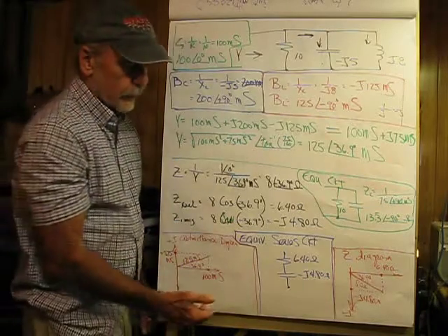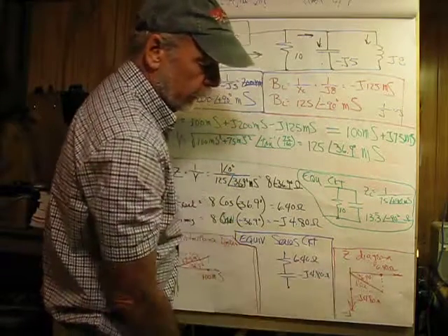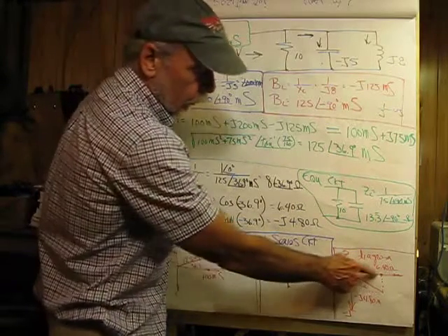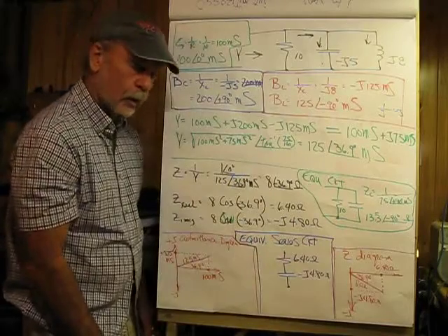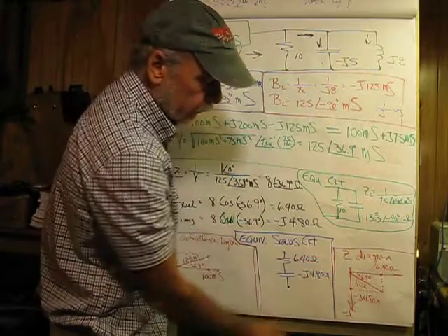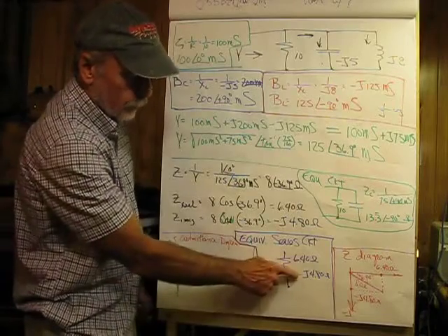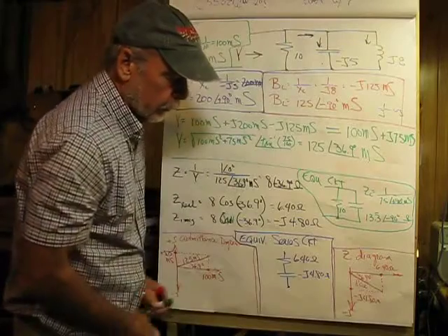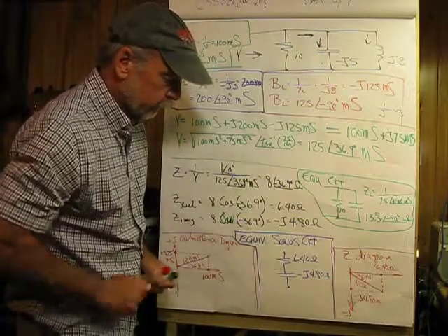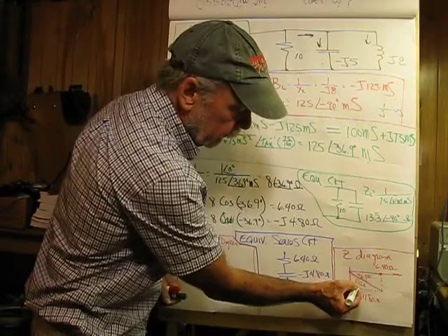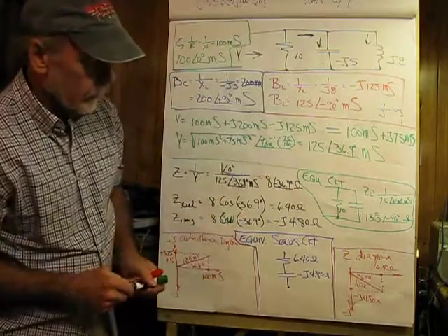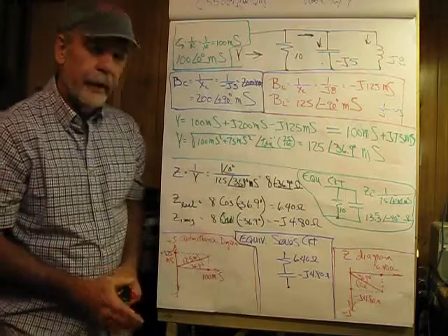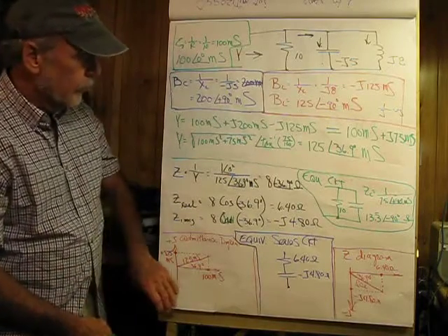So if we come over here, we can also come up with an impedance diagram. That's kind of business as usual. No surprises here. We're coming over on the real axis to 6.4 ohms, and down on the negative J axis to 4.8 ohms. Dot the box, draw the line, and what we end up with is 8 ohms, and the angle is, as suspected, 36.9 degrees.